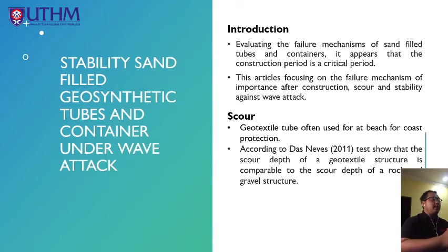For the next topic, I will talk about the stability of sand-filled geosynthetic tubes and containers under wave attack. For the introduction, evaluating the failure mechanisms of sand-filled tubes and containers, it appears that the construction period is a critical period. The second one is this article focusing on the failure mechanisms after construction: scour and stability under wave attack. The first subtopic is scour.